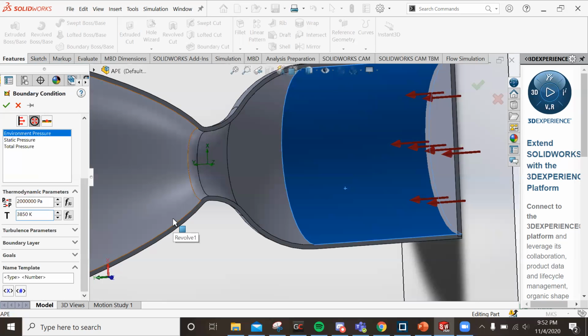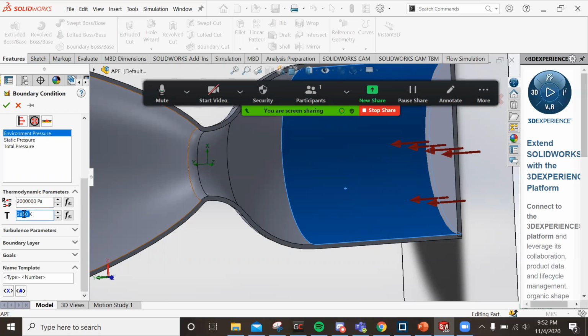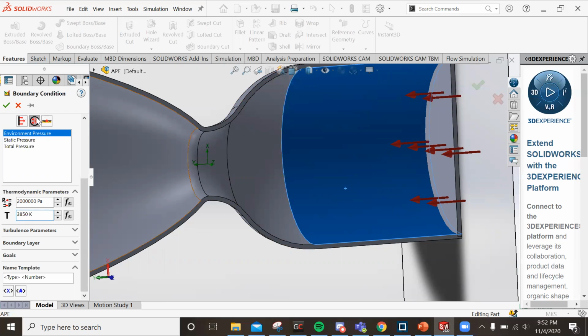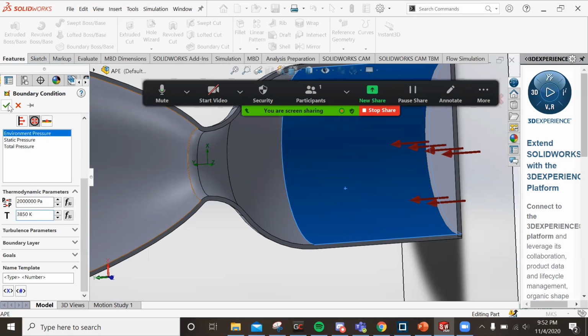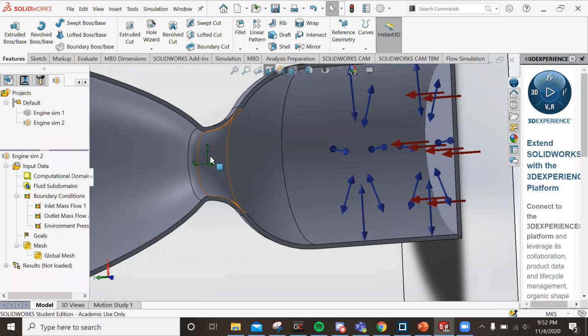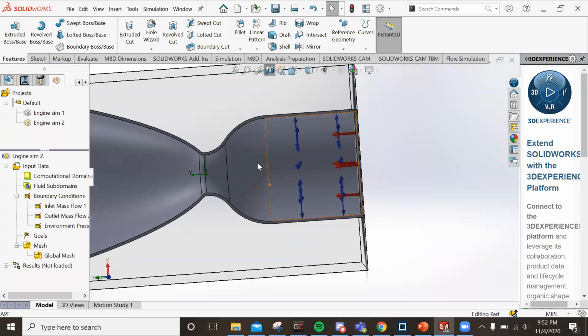Because one day you'll be doing a thermal sim and you'll forget to set this value, and your temperature values in the fluid are going to be very off, and you're going to spend like half an hour trying to figure out why, and figure out it's just because the wall temperature is the wrong temp. Anyway, that's definitely not a true story.